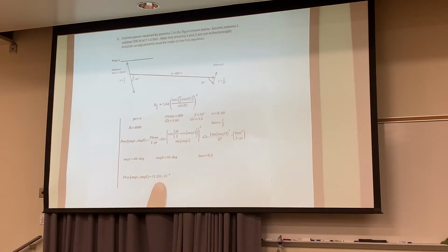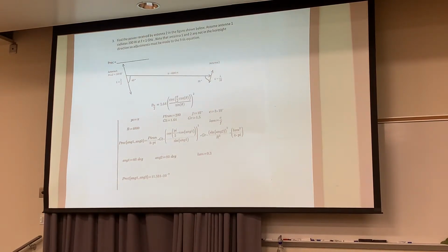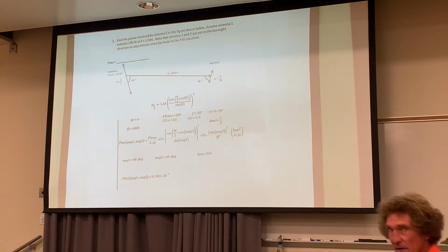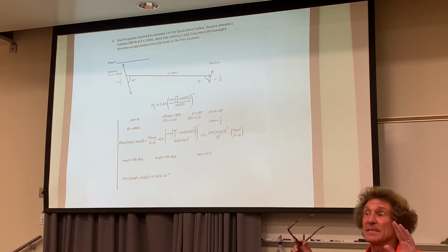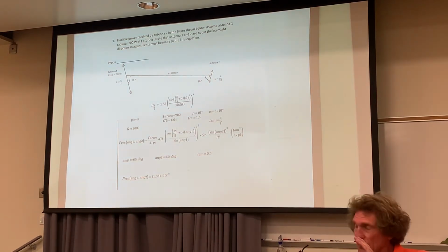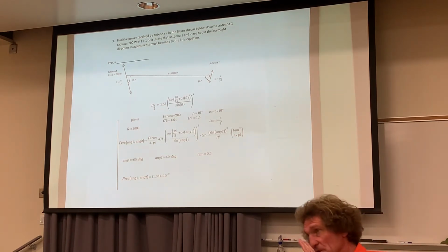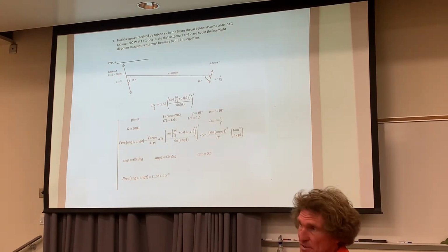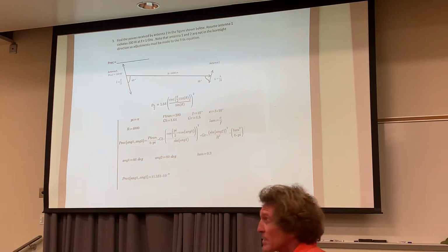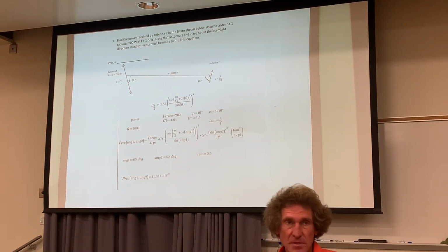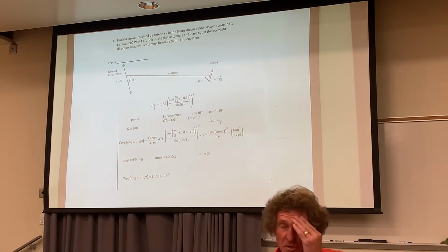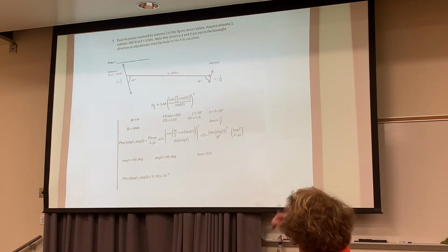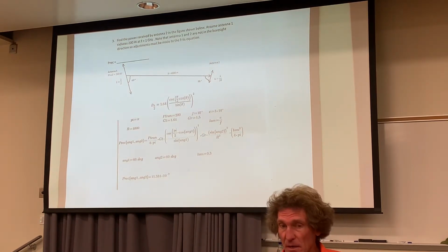You all see it, class? Because it's just the straight equation, it's the Friis transmission equation. It's going to be lambda over 4 pi r, squared, times the transmitted power, times the gain of the transmitter, which means you have to take into account that it's a half-wave dipole, and it's actually bent. It's not directly at broadside, 90 degrees, it's at, in this case, 60 degrees, or 120, either one gets you there. And then you multiply by the gain of the receiving antenna, which is simply 1.5 times the sine squared of that angle to the normal, which is 80. That's it. That was fair.